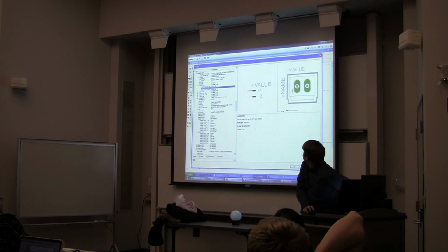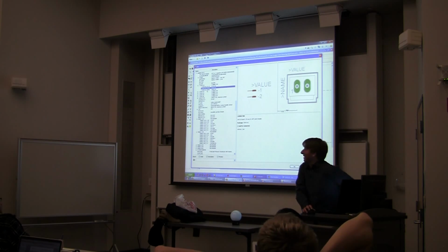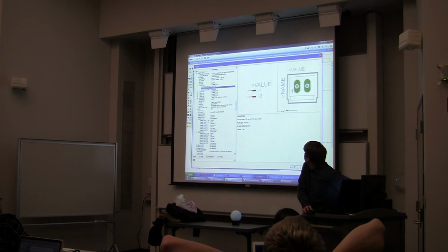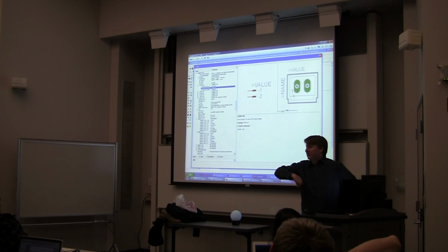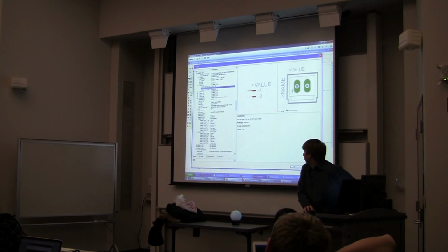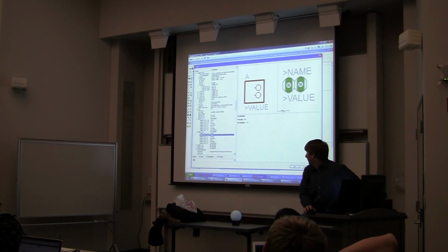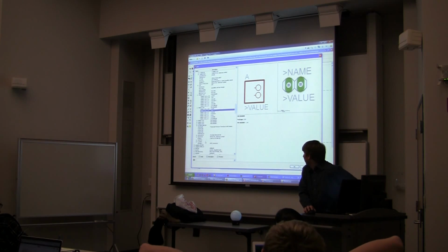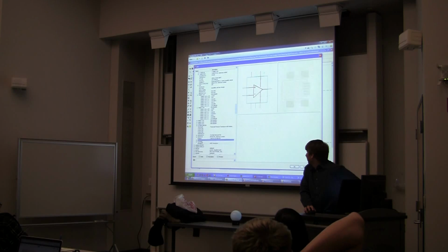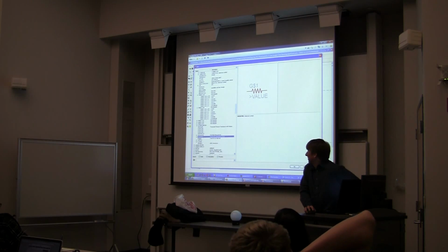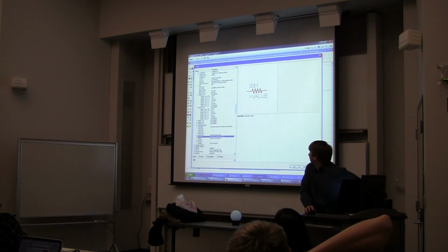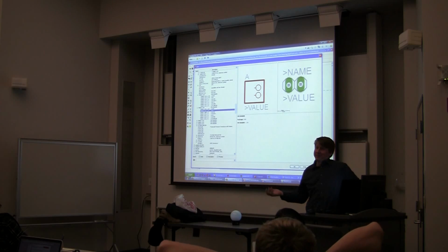Whereas these are secret. You can Google them, Molex sells them. They have these nice little plastic housings with connectors that only plug in one way. But if you're just going to mess around with something like a thermistor, you might just use a pin header and solder it directly. So in fact, if I go down here, there's no thermistor. And so I say, oh no, what do I do? Well, I'm going to use the thermistor I got in my gadgetry kit.